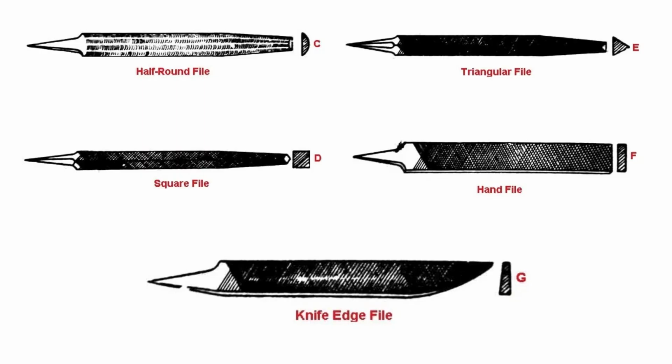When you have a triangular file, it is triangular in shape and its angles are 60 degrees. It is used for filing V slots, and square and rectangular jobs of about 60 degrees and below 90 degrees are done with this file. It is also known as a three square file. Now you have a square file. This is somewhat tapered, and filing of rectangular square grooves, slots and keyways is done with this file.